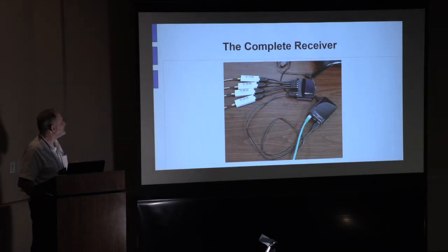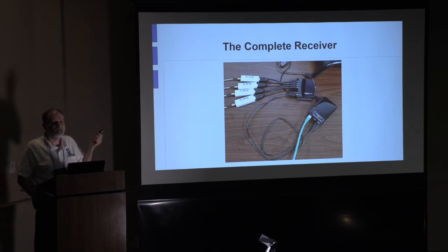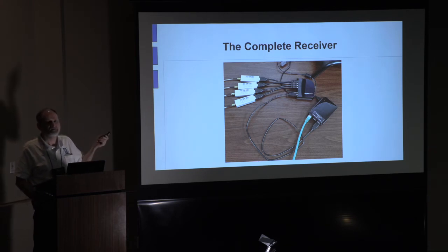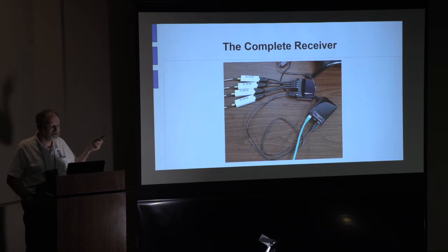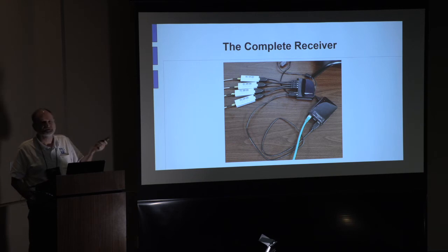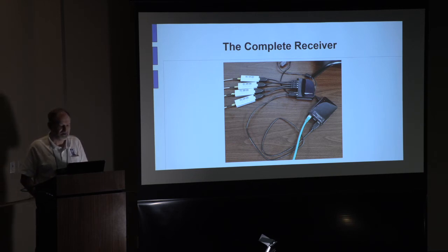This is the complete thing with 4 receivers. And this is running right now at the N8ZM contest site about 40 miles north of here. One dongle's on 6, one on 2, and there are 2 on 432, because to cover both the CW and the beacon portions of 432, it's beyond the single 192 kilohertz bandwidth. But that's kind of all that's involved in doing it.